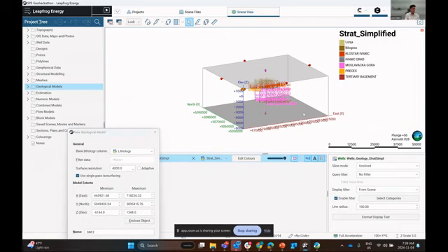And one of the advantages of utilizing Leapfrog, especially in a geothermal environment, is it gives you the flexibility of constructing the types of geology that you want. Because we're not constrained to a predefined geocellular grid, you can create curved surfaces. You can manipulate those curved surfaces based on seismic interpretations and your own manual interpretations based on the type of geology that you're actually trying to represent.